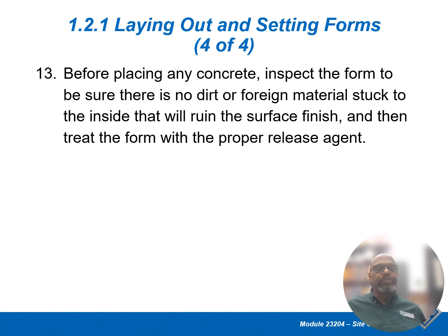Number 13, before placing any concrete, inspect the form to be sure there is no dirt or foreign material stuck on the inside that will ruin the surface of the finish. Then treat the form with the proper release agent.